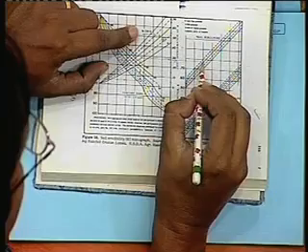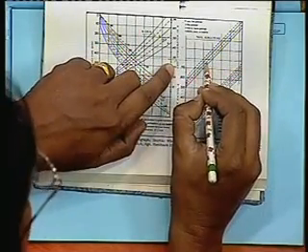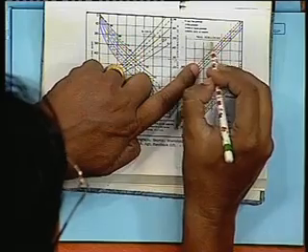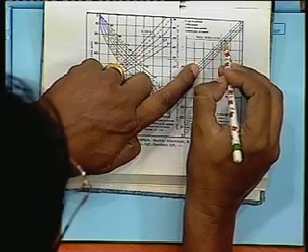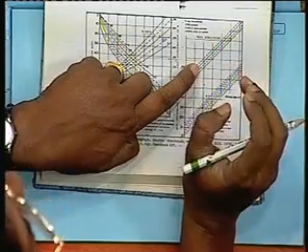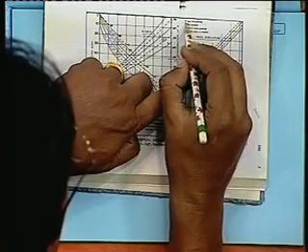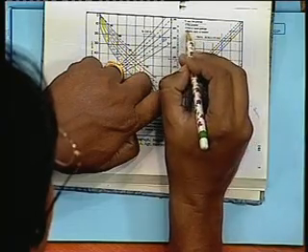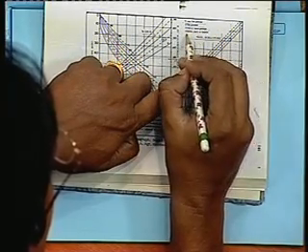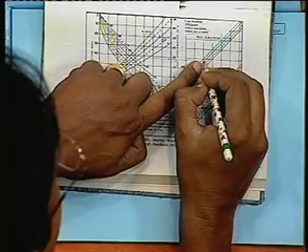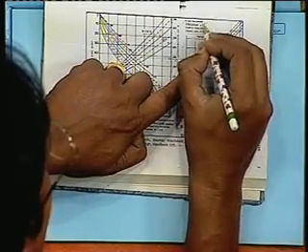To further refine this value of K, we generally run to the map for soil structure, which is given as 1, 2, 3, 4. 1 is very fine granular soil structure, then fine granular, medium or coarse granular, blocky, platy or massive. So here our soil comes under fine granular.